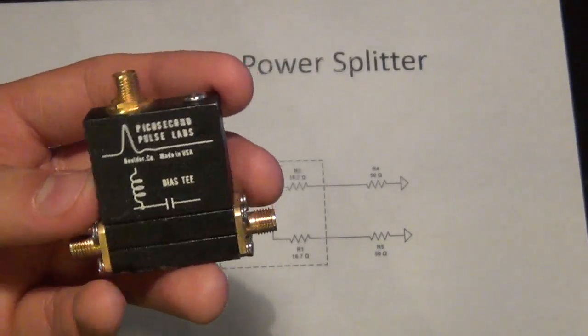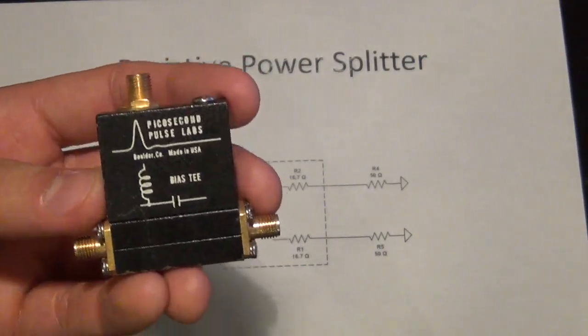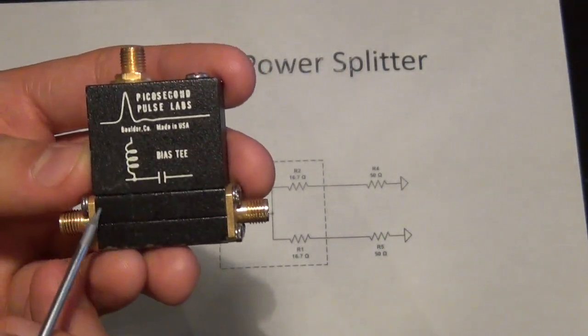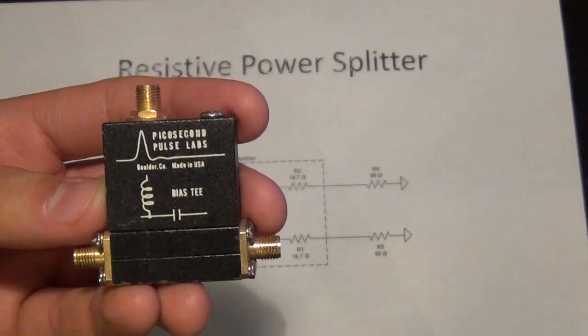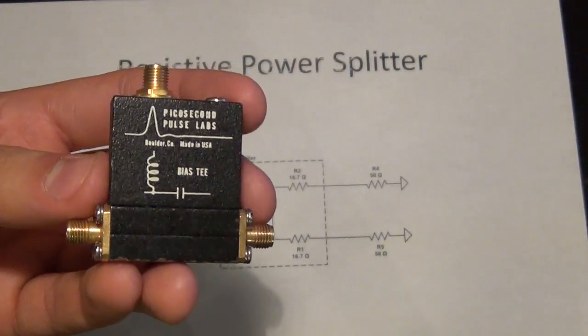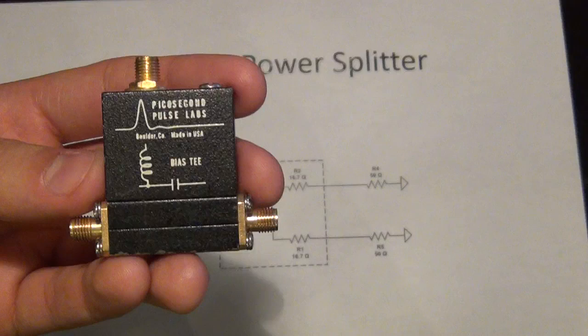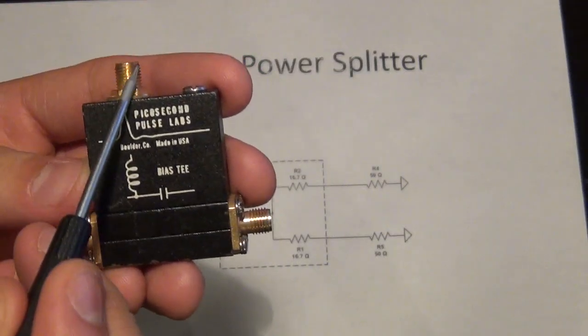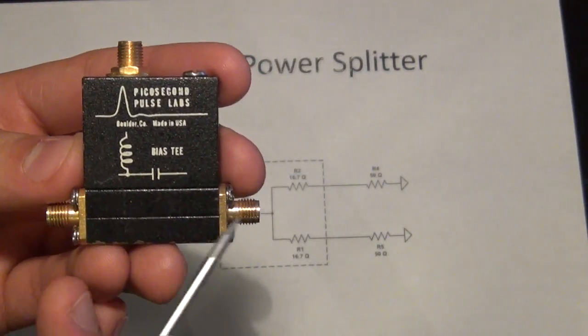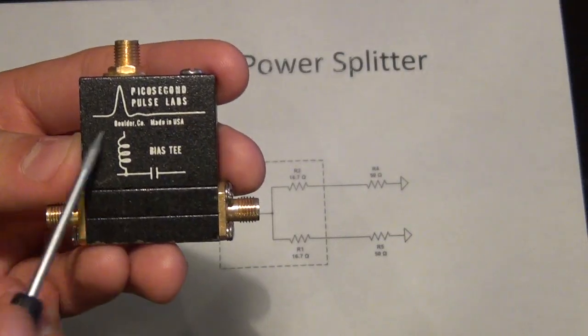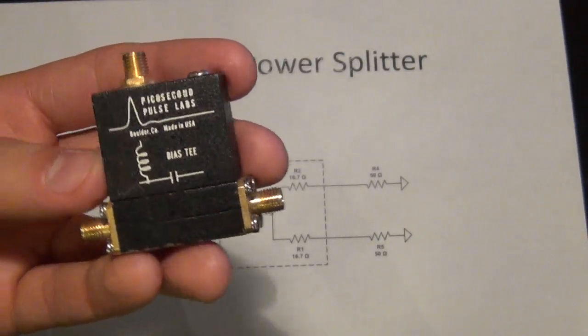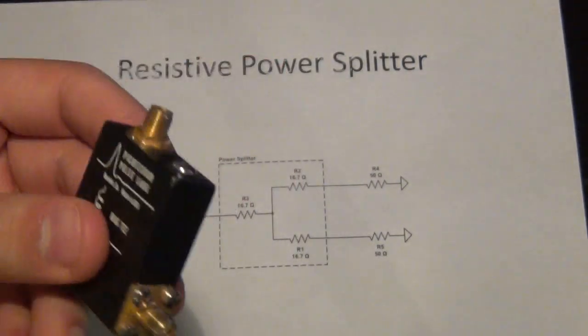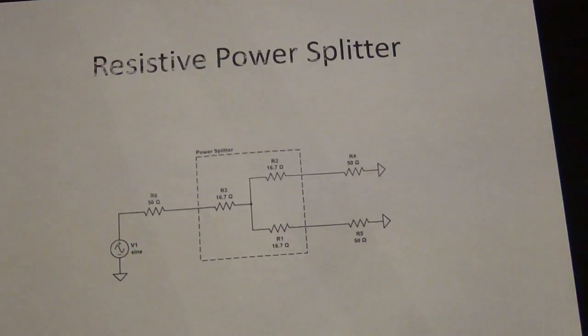This is a very, very useful component used all the time if you want to measure the DC voltage you have, or you want to apply a DC voltage to an input of an amplifier. If the input of your amplifier needs some DC voltage to bias, you apply DC voltage here, you connect this to the input of your amplifier, you connect this to your AC signal source. So you're separating your AC and DC path. Now this may seem really simple, but it's actually quite complicated to make one. Let's take a look at what things can go wrong.